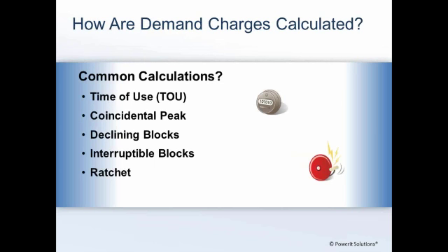that you would have to be reducing your power. And then the last way that they calculate demands are ratcheting blocks, where you may have a price range for 500 kW, a price range for 1,000, 1,500, so on and so forth. And then as you would exceed, let's say you were in the 1,000 kW, but if you exceeded that, you would ratchet up into the 1,500 kW block, and then you would be responsible for the next 12 months of paying for a portion of that from 1,000 to 1,500 because they would have to have it available for you even if you weren't using it.